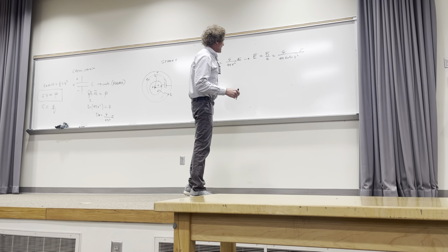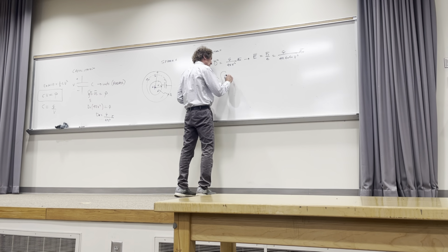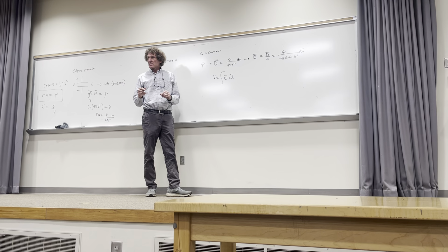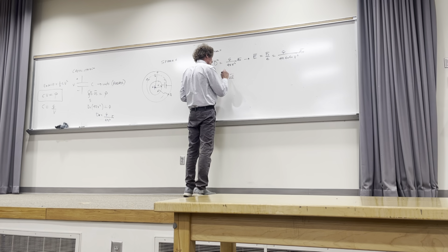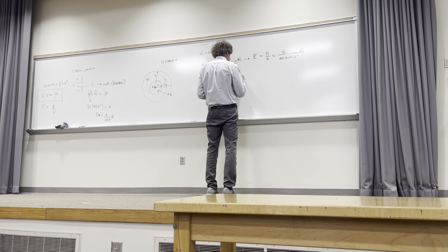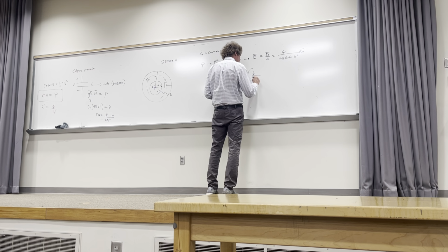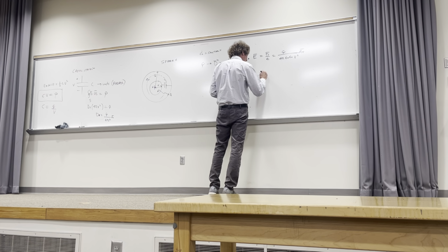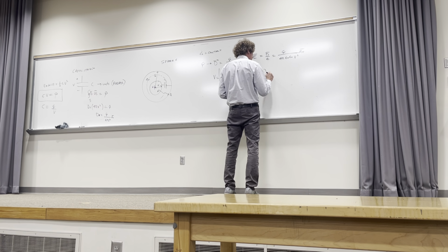How do you get the voltage always? Integral of E dot dl, correct, class? I didn't put any limits there, but I know I'm going from the inner to the outer radius. I might as well put an absolute value because I know it's got to be strictly positive. So for that case, I'd be integrating Q over 4 pi epsilon naught epsilon r, AR divided by r squared, and then it's dotted into dl, which would be AR dr.